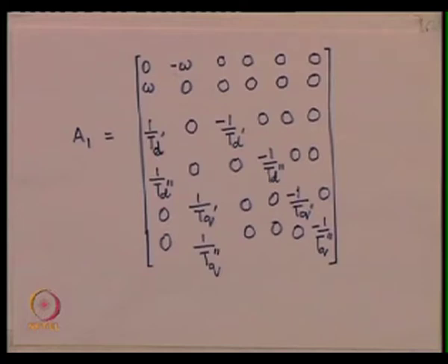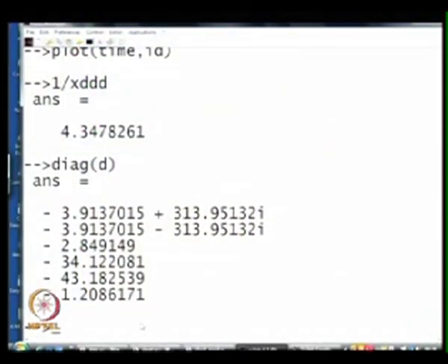In fact, you can formalize this by looking at the participation factors corresponding to the states, which we discussed around the 8th or 9th lecture of this course. You can look at the participation of various states in these eigenvalues. We will not get into the complete study of the participation factors, but you can guess that psi d and psi q are primarily associated with the complex pair of eigenvalues, the first two ones. That is just a bit of guesswork.